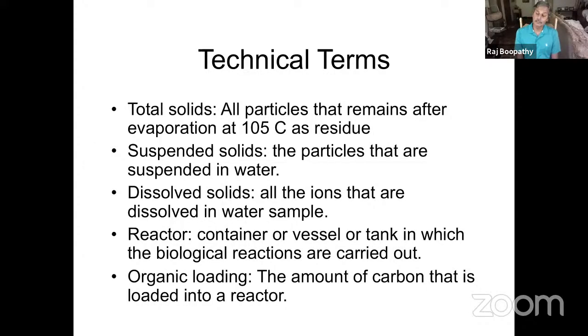When the receiving water body gets turbid, that's going to affect the light going through, and that's going to affect photosynthesis. So you need to make sure your solids are less when it is treated and let go. Total solid is basically all particulate matter that remains after evaporation at 105 degrees as a residue.